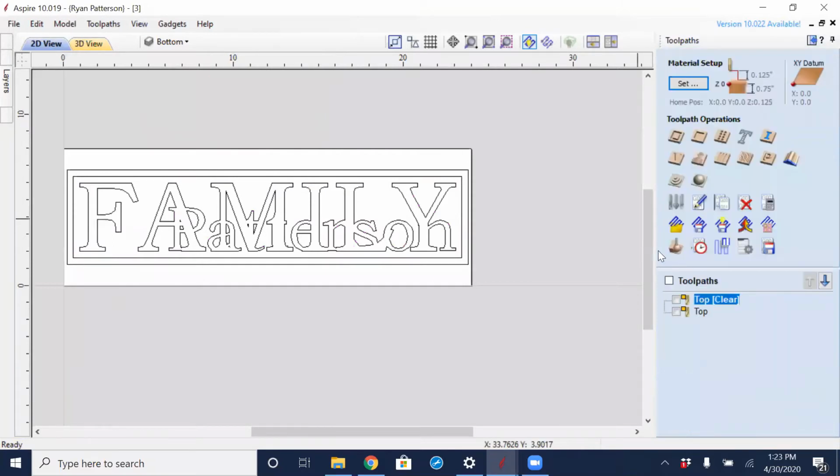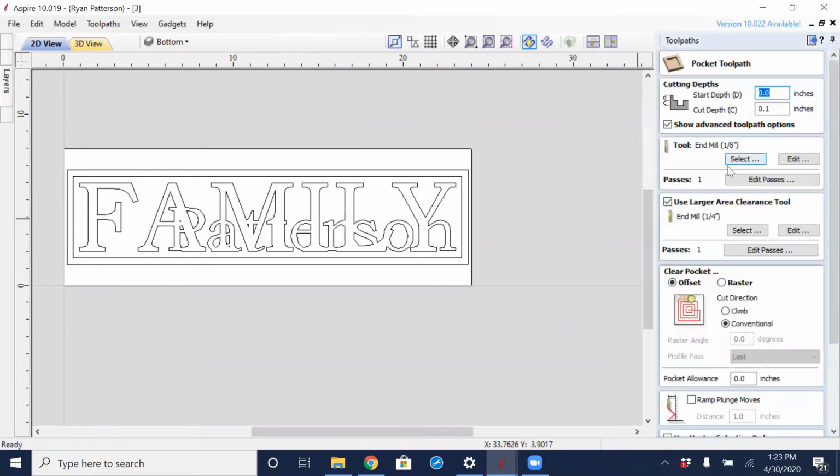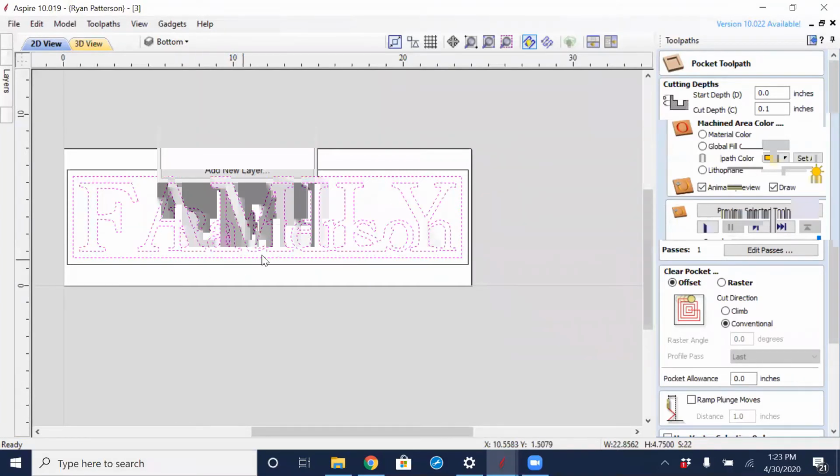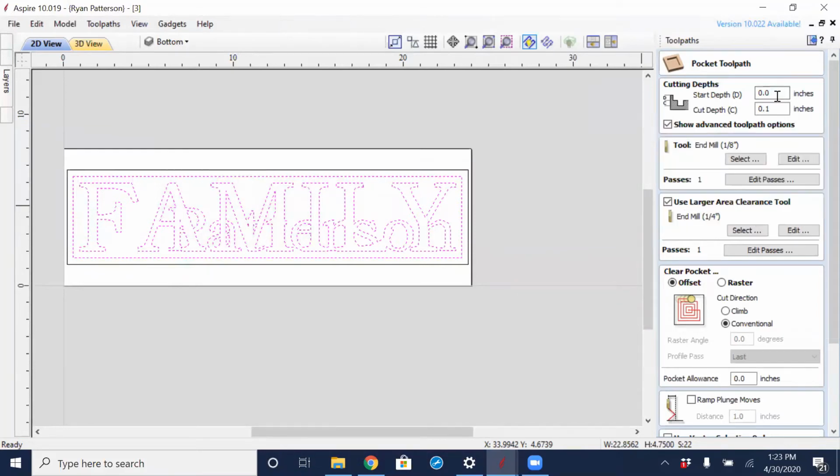And going to run the similar pocketing toolpath, going into create a pocket toolpath, selecting the inside border, and then all of the objects that I want to pocket around. We have a 1/8" cutter, just the same way as used before. Our cutting depth in this next layer, I also want to be this 0.1. Now we've already removed 0.1 material across here. So there's two ways that I could do this. One isn't necessarily more correct than the other. So we'll do one first.